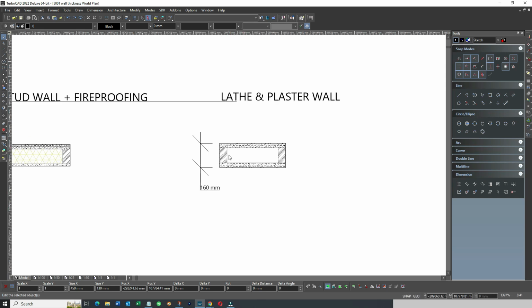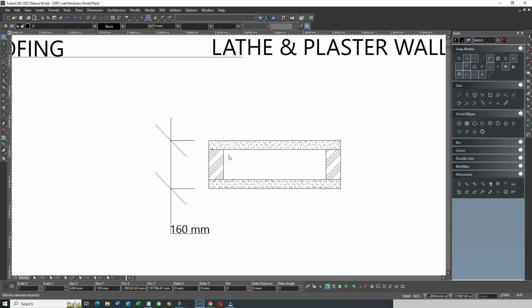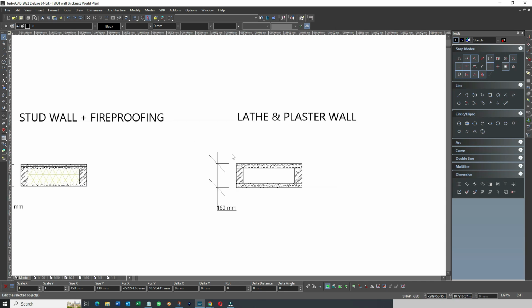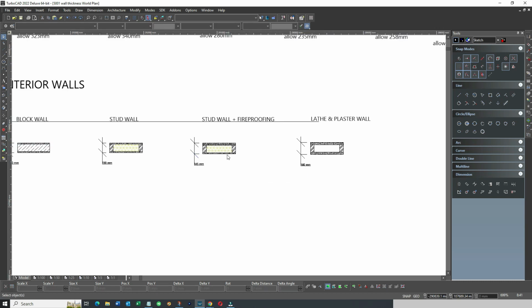It's a good lesson. Then I also thought let's mention the old lath and plaster wall, which is in Victorian houses. Ones that are really messy and dusty to remove. On those, 100 mil inside is about right, as in the stud. And then the laths and the plaster, well, we find the lath and plaster is definitely thicker, so we allow 30 mil on both sides. So on an old partition wall in a Victorian house, we would allow 160 rather than on a new one, which would be 130. So new stud wall 130, old lath and plaster wall 160.